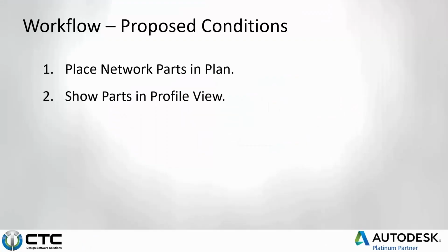So, what about the proposed conditions? Well, we're going to start off in a pretty similar fashion. We're going to place our networks in plan view. And since this is now the design phase, it's also pretty helpful to have these around in a profile view as well. Depending on how you like to look at things, maybe this is the center line of your roadway, or maybe you create a new alignment based off of your network parts so that you're not messing with any sort of distortion for being 20 feet away at -2% or things of that nature.